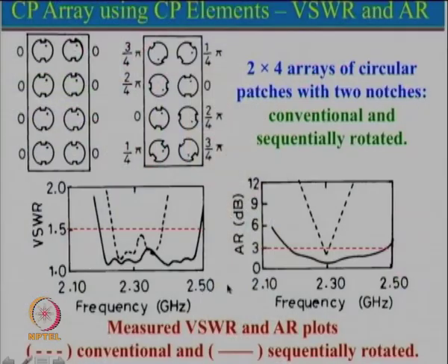So, then we had to study, we did study, we simulated these things, we did the experiment, and now I want to tell you what the disadvantage of this particular configuration is. This particular configuration has a relatively lesser gain compared to this particular array here, because here all the elements are radiating together. The contribution towards the broadside direction in this narrow bandwidth, all of them radiate in a similar fashion, so they give rise to better gain.